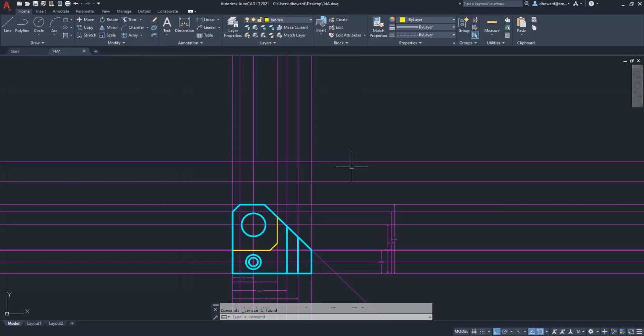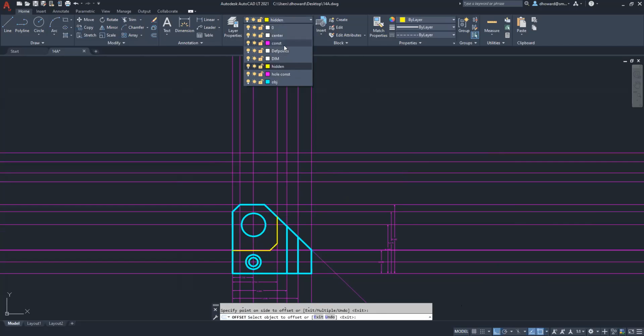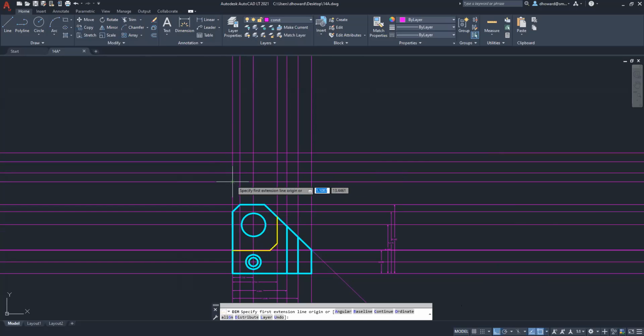We then have another offset, which is the thickness of this octagonal protrusion, and that's 3/4. So I'm going to O enter 0.75 enter. So that'll be that part. I also have that slot cut, which is 3/4 from there. So if I show all of these guys to you, what I just did, the initial offset is this 1 3/4. Let me zoom in on that a little better.